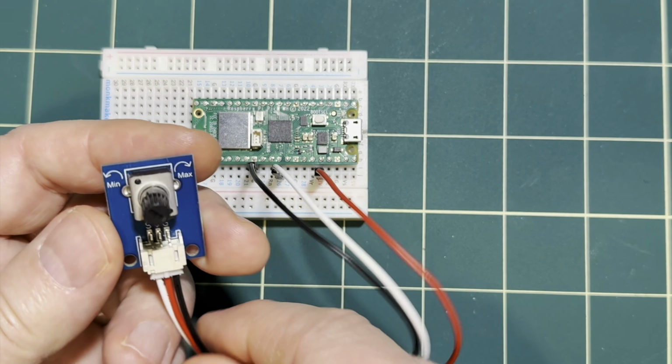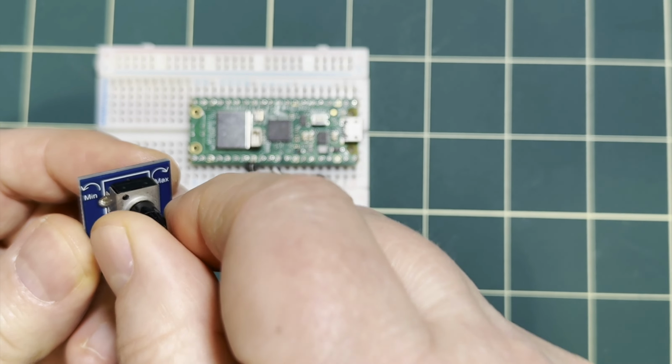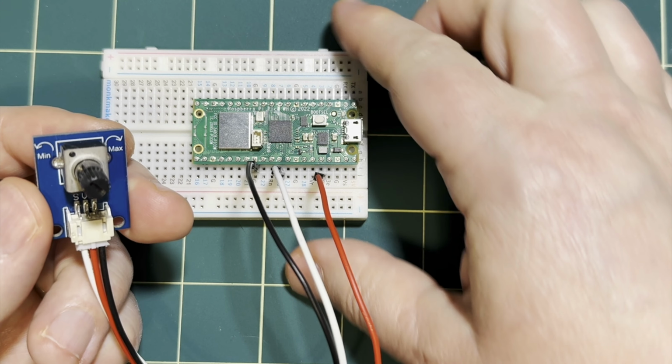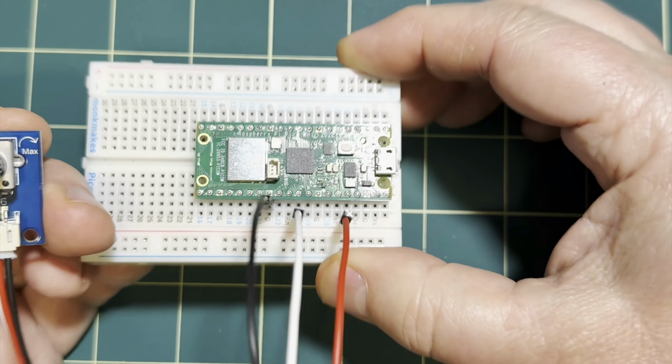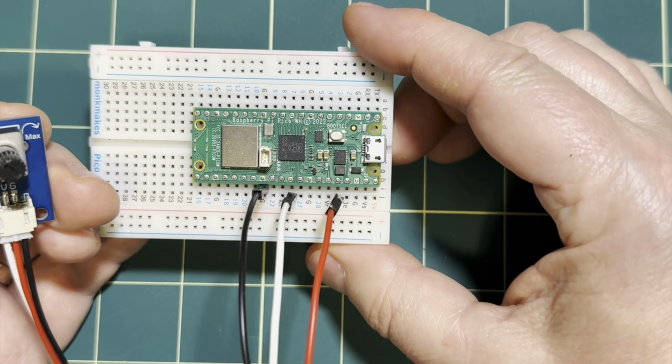And here's the setup of the potentiometer breakout board. The jumper wires are heading into the same locations on the breadboard, but note the key difference. The signal wire labeled S is on the far left. It's not in the middle in this configuration, so make sure you wire it up right. And again, you can use any of those 3 analog pins for your signal. Just make sure that your power goes into 3.3 volt.